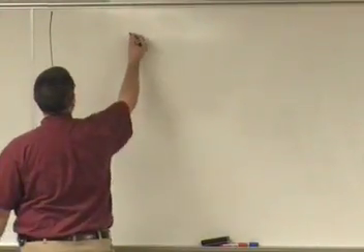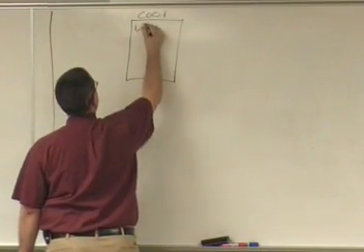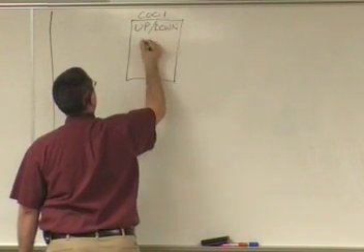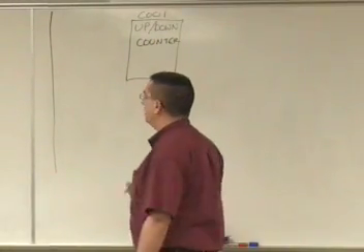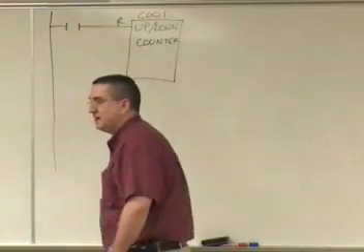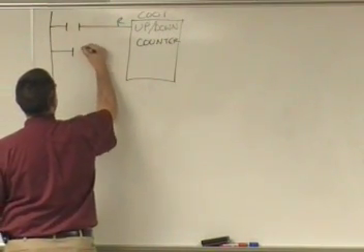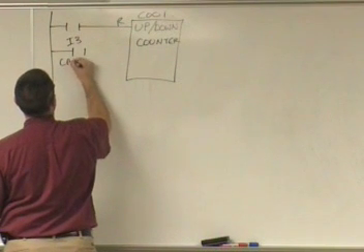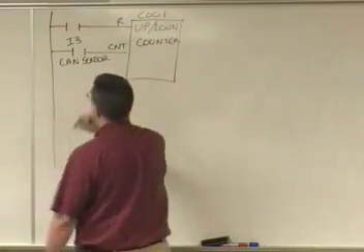Let's see. All right. So let's say I have an up-down counter. Let's say I have a C001. This is my up-down counter. And let's say that coming into the reset pin, I have something, I don't know what it is yet. I'm just going to run it into the reset pin because eventually I want to reset this thing. Coming into the count pin, I know that I have a sensor. Maybe it's I3, this is my can sense.